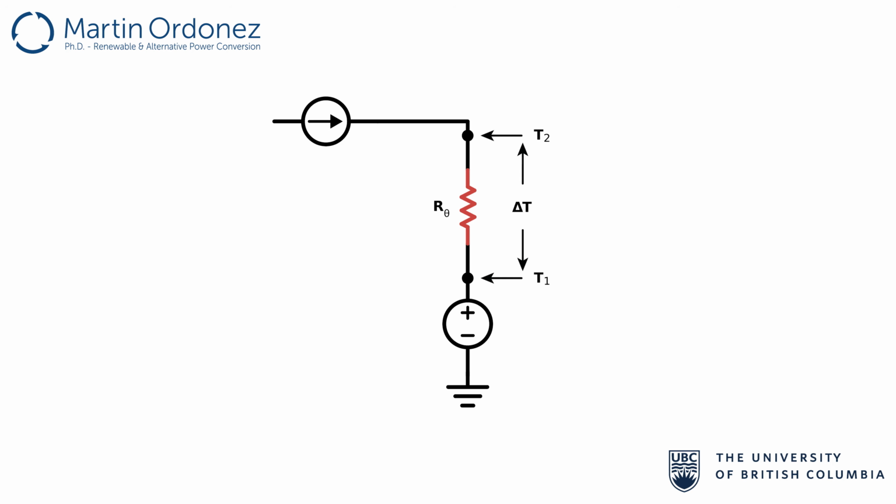In order to solve the thermal problem and find the junction temperature value, as mentioned before, we need to know the thermal resistances and the power losses, which act as the thermal source. For determining MOSFET losses, you can watch our video on power loss calculation.